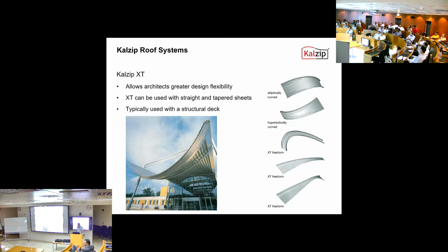You can get from your computer a beautiful top sheet, but if you don't design what you put underneath properly, the aluminium is very flexible. So while fixing it on site, design intent, for example, is a curve, then going down and curving again. I have seen one of the projects. You see it coming, stopping, and continuing. Why? The sheet is done nicely, but what is under it was wrong. So it's a full learning process that you need to do. It's not by buying or developing a 3D machine that you are really having that 3D capacity. All that is underneath is as essential as the sheet itself.